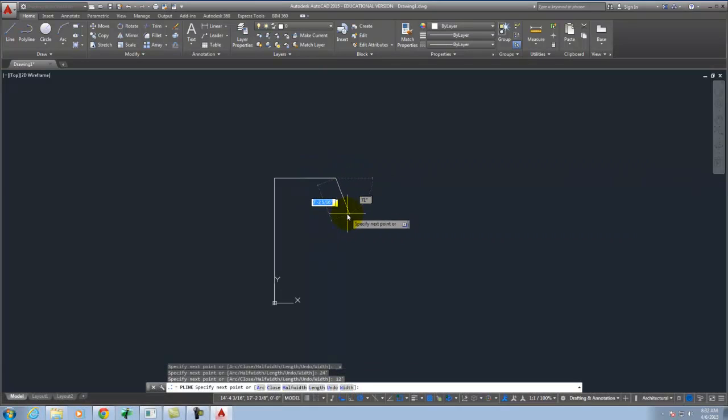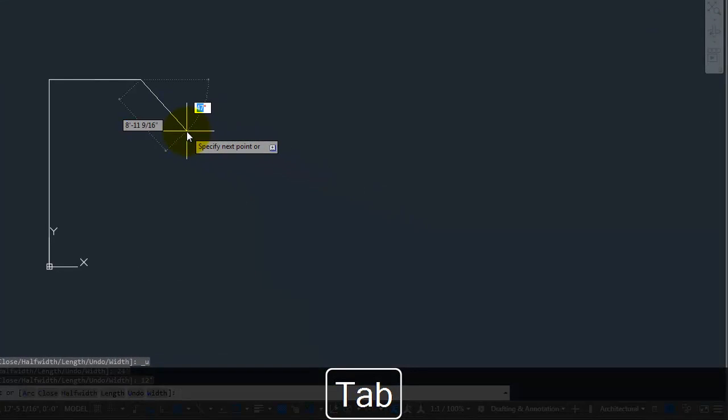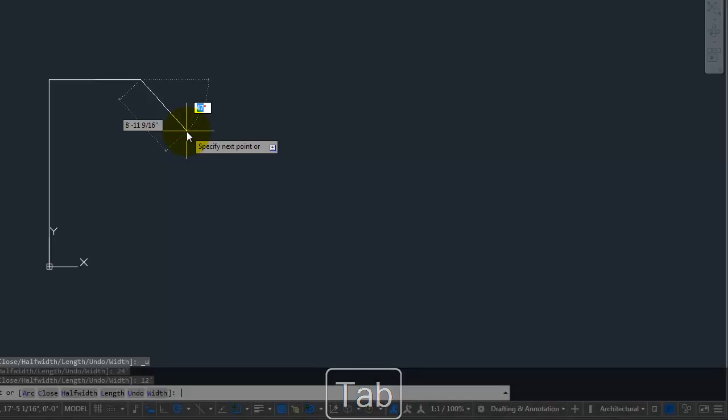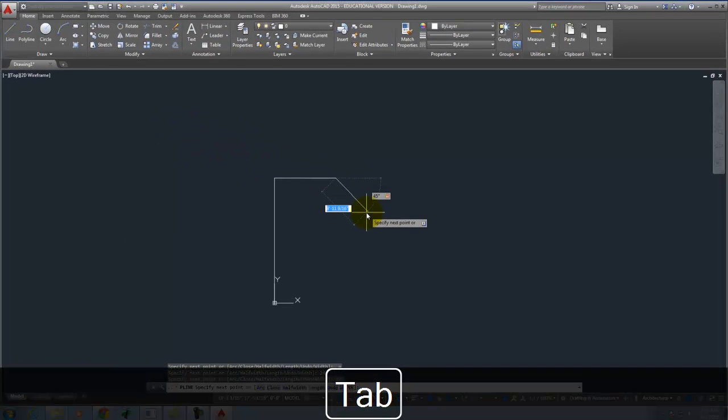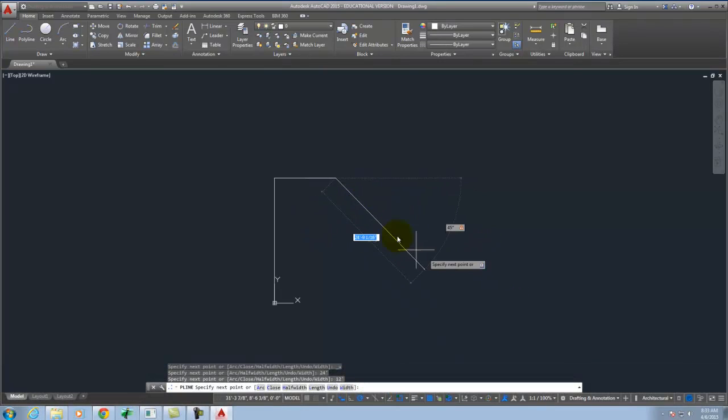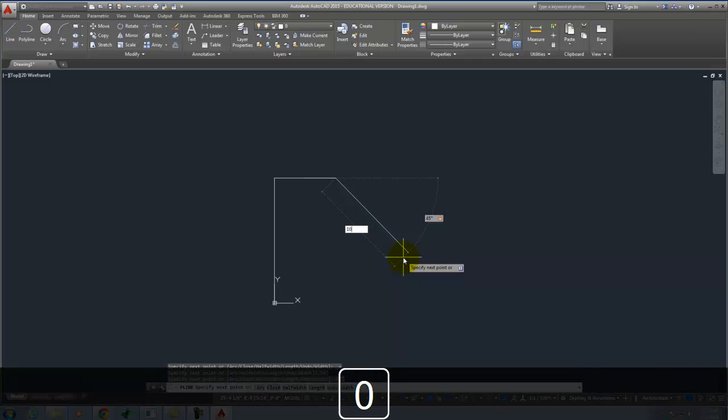If I wanted something to go on an angle, for example, and I wanted to be locked into a particular angle, I can press the Tab key, which is going to switch from the length field into the degree field. Okay? And I could type 45, for example. And now everything that I draw is going to be locked in at that 45 degrees. And I could specify a given length. So, I don't know, 10 feet.